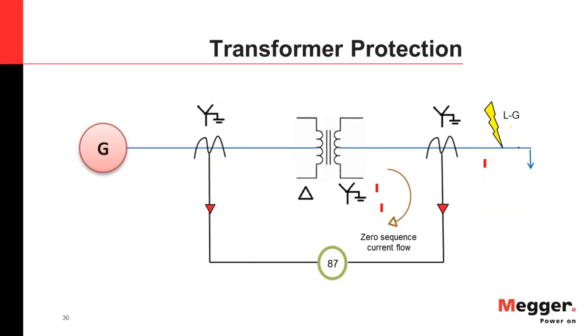I have seen that being employed in the Schweitzer 787, 587, 487 relays, and some of the GE Multilin 740 transformer differential relays. But I have not experienced a wide variety of manufacturers' relays till now. The relays that I have seen use zero sequence elimination.